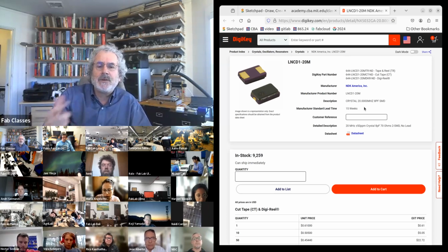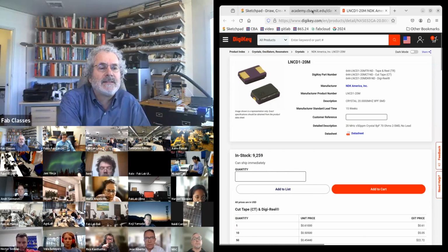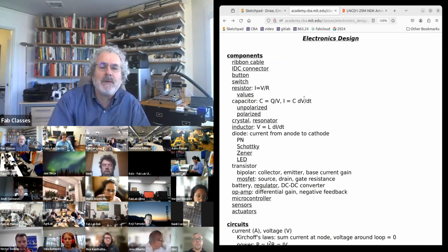Many of the processors we use don't need these. They have an internal source of time, but it's not as accurate as the crystals. The crystals can be parts per million rather than a fraction of a percent.